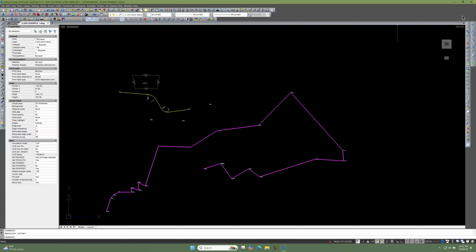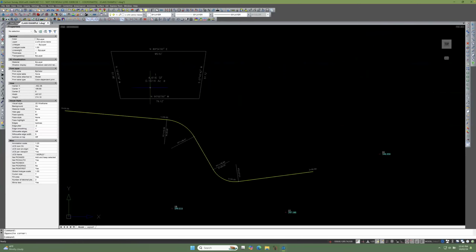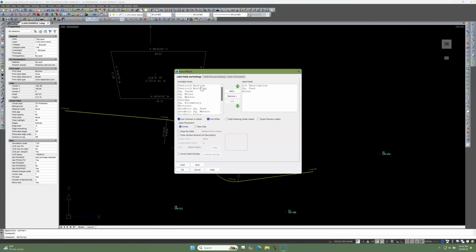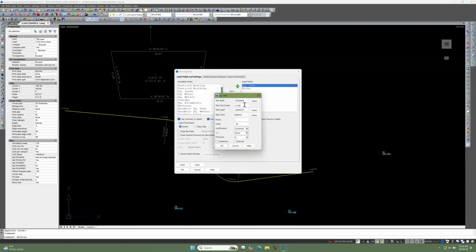I actually have one question real quick. Okay. How did you get the acreage again? I got it annotated, but I didn't know how to get the acreage in the middle. It was in my area layout, my area defaults, and that's where we set all this stuff up. In my area defaults, I brought all of these different available. Once I'm here, my square feet, if I double click that, I said, I want to make my square feet to the nearest single square foot.